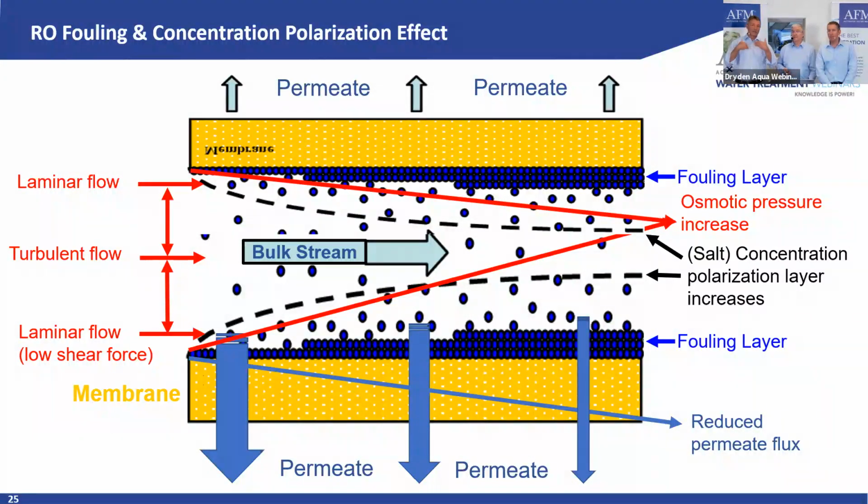So my understanding is that the osmotic pressure will go up over time anyway because of the salt concentration, but that will be highly increased by this fouling, particle and biofouling. Yeah. And this is where you have to go from 70 bars to maybe 72, 73 bars. And at that volume, that will be a big increase in energy consumption. But not all plants can increase the pressure. The consequence is that you will lose more and more of your water productivity. That means you will have less water going through, which you can see on the downstream of that element or of a system.